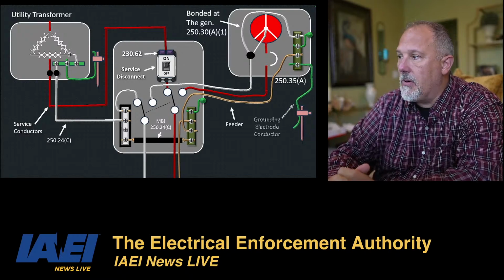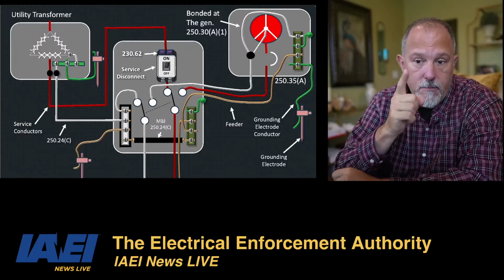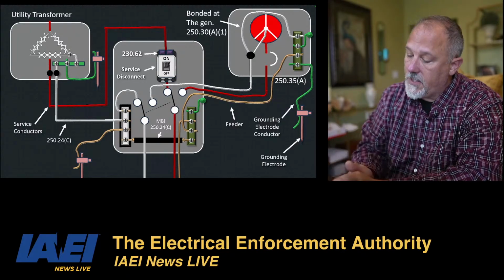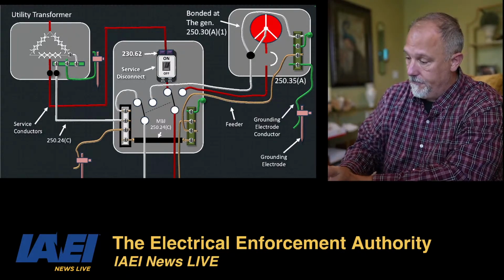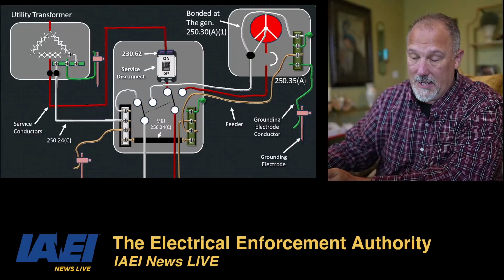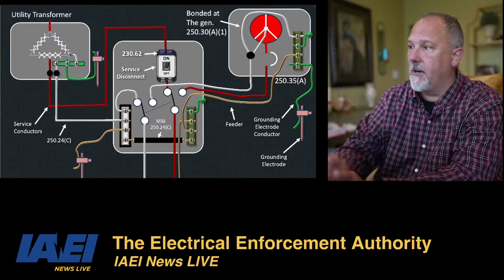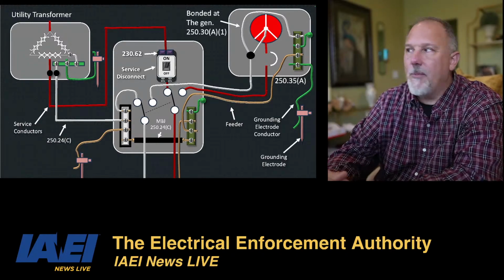So now I'm going to pull in my feeder. It's a feeder from the generator. That's not a service. Remember, a service is defined and it's related to a utility. That is not a service. That is a feeder. I'm bringing my bare copper conductor over.